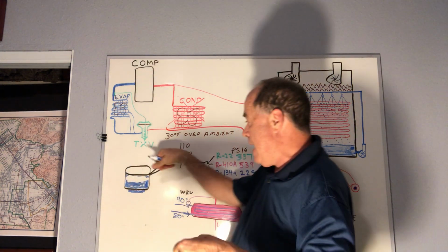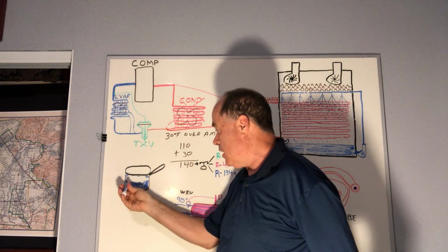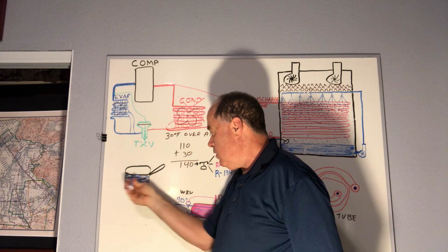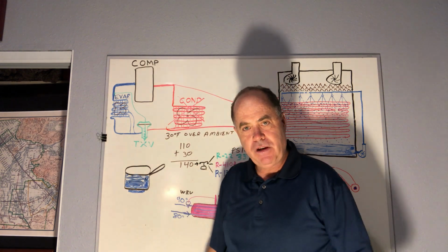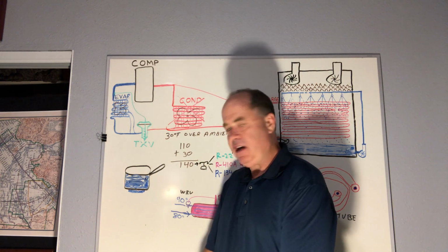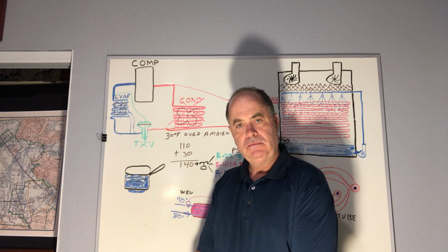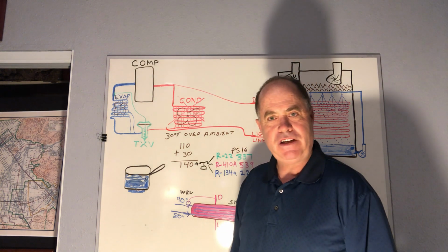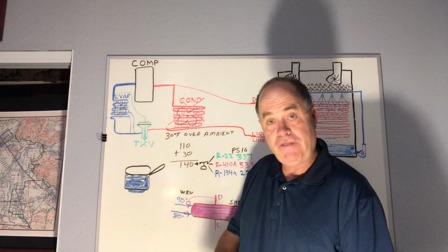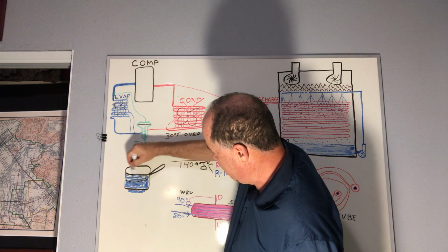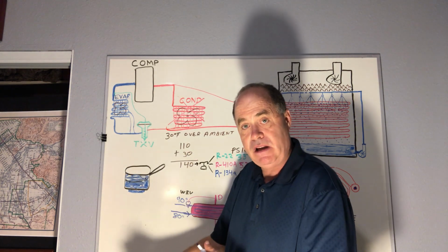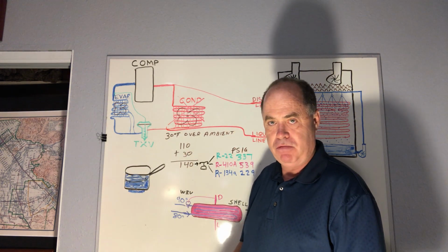Now, if we went over to the tap and filled it back up with tap water, think now, see if you can figure this out. What now is the parts per million in the pan? The answer is 750. Because remember, the water coming in from the city was 500. So this was the 500 up here, and below here was 1,000, and equal parts, if you mix the 1,000 with the 500, you get 750 parts per million.